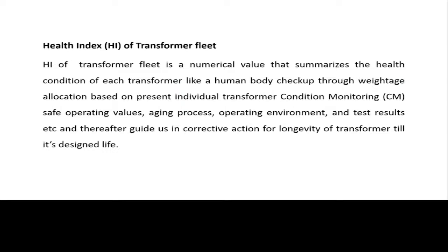You mark each and every word in this health index, which I try to define. Health index of the transformer fleet is a numerical value that summarizes the health condition of each transformer, like a human body checkup, through the weightage allocated based on the present individual transformer condition, monitoring safe operating values, aging process, operating environment, and test results, etc. And thereafter it guides us in corrective action for longevity of the transformer till its design life. So I think each and every aspect is covered here. The health index is a very important tool available to all the utilities.